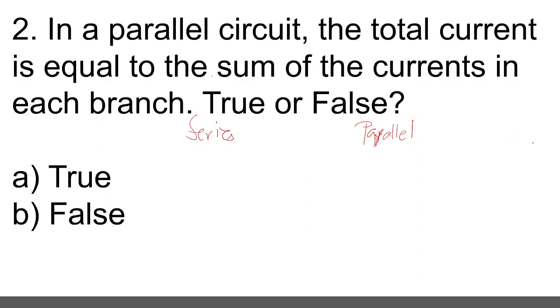Now, in terms of quantifying or calculating the current, voltage, and resistance, we only have two types of circuit, the series and parallel. You have to understand that we have IT, VT, and RT. So with this one, you have I1 is equal to I2 is equal to I3.